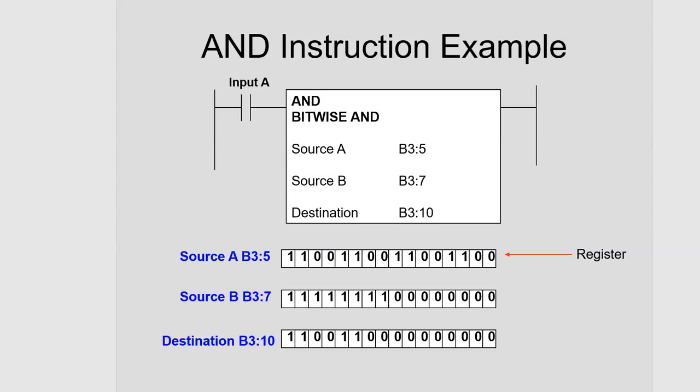So what you see here is an instruction that will exist in your simulation software. And remember what we said, on the left here we have inputs, and the last thing on every rung is an output. Now this is actually an output. This is a command. This is the bitwise AND. So what that means bitwise is you take a whole register and you take another whole register and you can AND those bits together. And bitwise means the corresponding bits are ANDed, and depending on if you have trues or falses in that third register, you'll store the result of that AND.